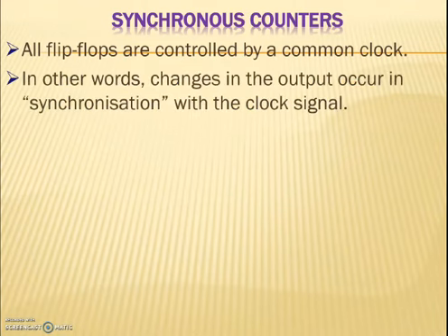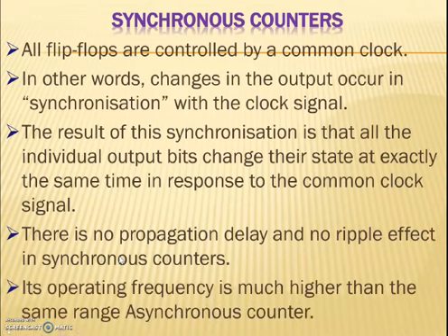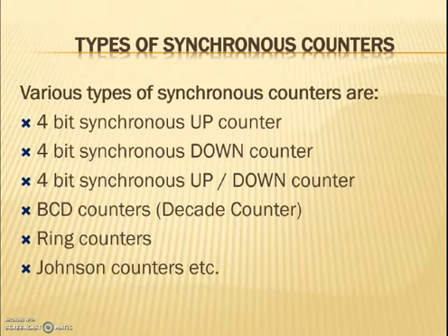We already know that all flip-flops here are controlled by a common clock. In other words, the changes in the output occur in synchronization with the clock signal. The result of this synchronization is that all the individual output bits change their state at exactly the same time in response to the common clock signal. Because of this, there is no propagation delay and no ripple effect in case of synchronous counters. The main advantage is its operating frequency is much higher than the same range of asynchronous counters.